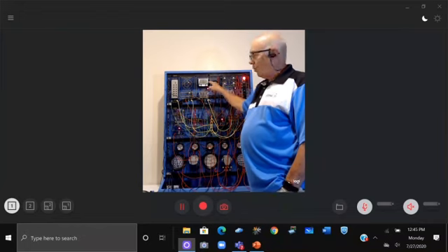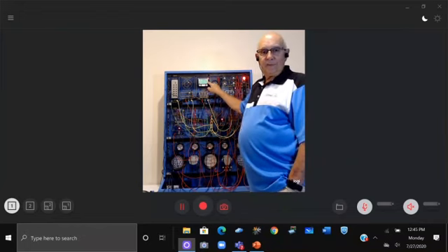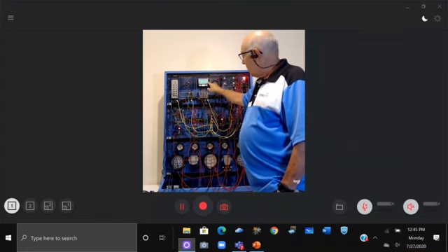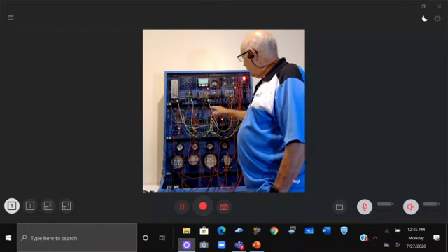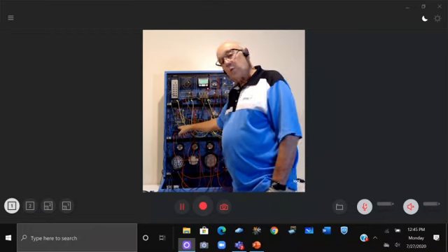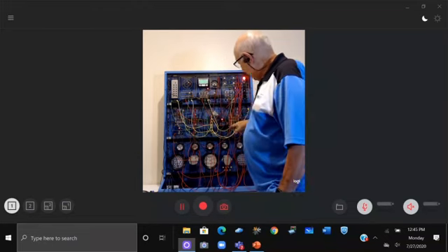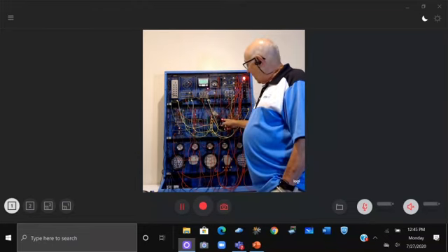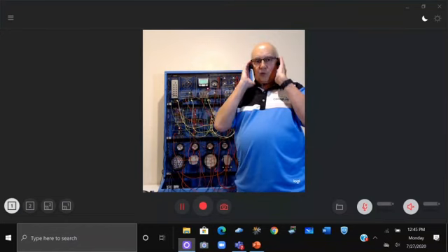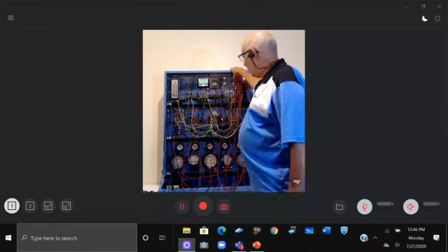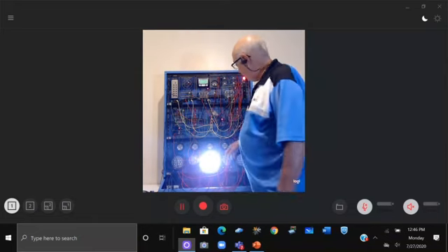One of which, probably relatively easy for you to see, the display lit up. CAN bus is now up. We now have a light on the input module, the engine control module, which we had before. We now have a light on the instrument cluster, and now we also developed one on the output. This system is up. It's sitting there, ready to function. Now, if I go and turn on the backup light, it works.